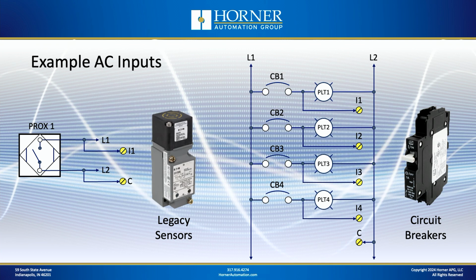Another scenario where we're dealing with AC is where we have maybe a series of circuit breakers, and we want to tap into the wiring after the circuit breaker so we can detect whether we have voltage flowing through that wire or not, or current flowing through that wire, I guess would be more properly said. So that's another scenario, the output of a circuit breaker, where we might want to tap into an AC signal and be able to interface that with our control system. These are just a couple of different scenarios.